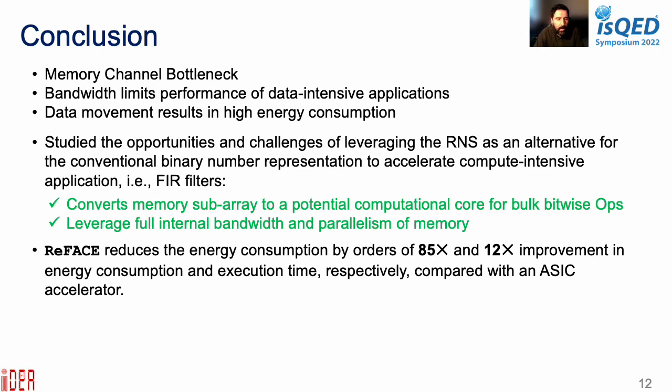As a conclusion, we propose a systematic methodology to implement efficient RNS FIR filters using processing in memory architecture to address these three main issues and also accelerate the processes. Here, because of PIM-friendly architecture and RNS, the arithmetic operations, multiplication, accumulation, are performed on a small residue independently and in parallel.